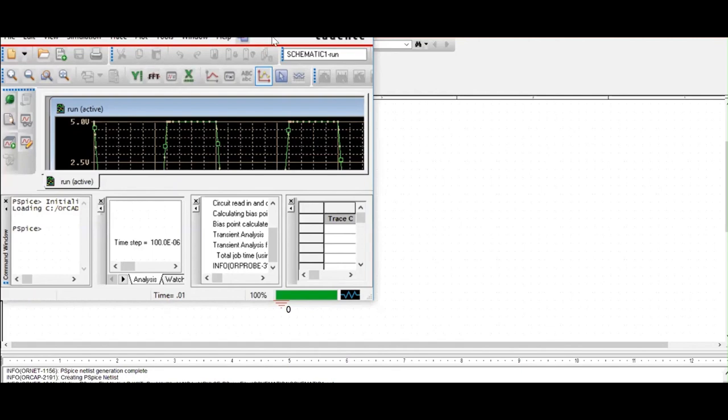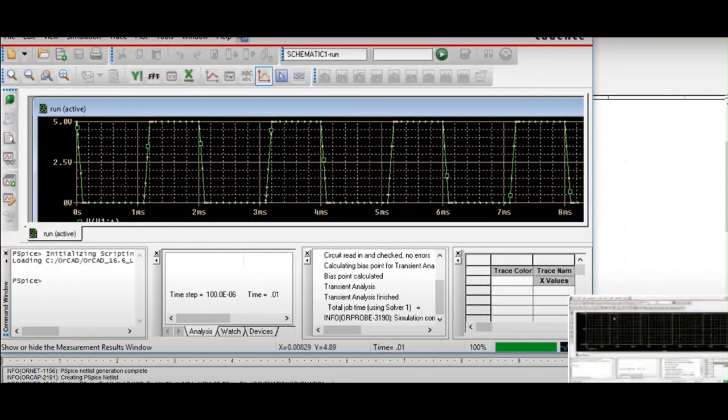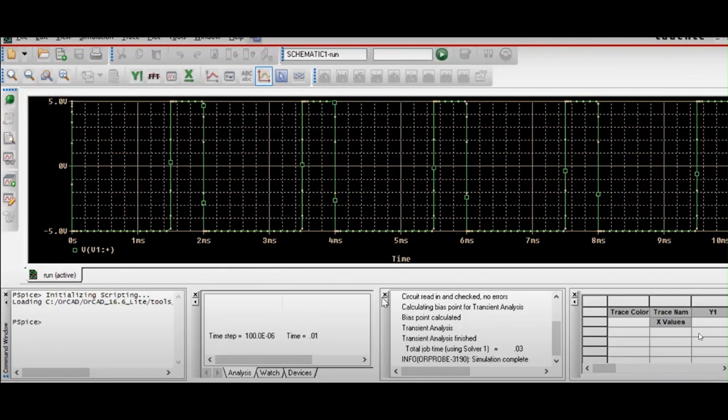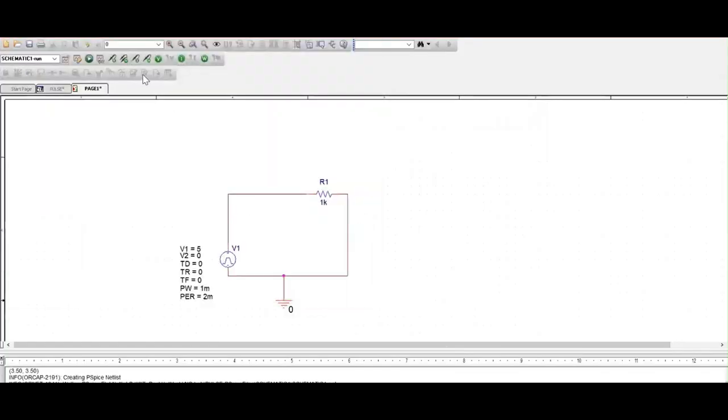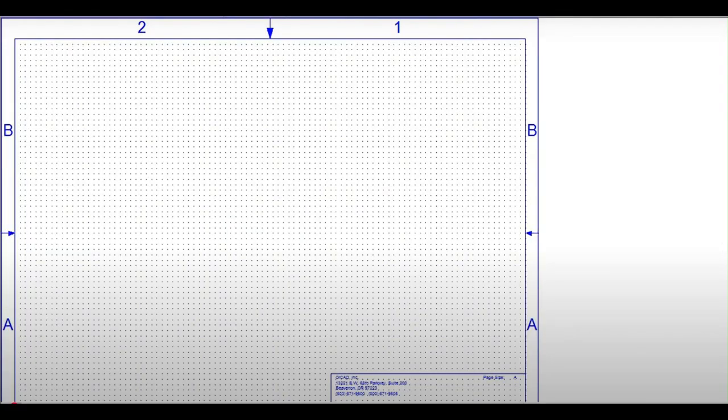Let's go for R-2R, which is a DAC, which basically converts digital data to analog data. If you give it a digital digit like 100, which is equal to 4, it will give you an equivalent voltage, which is 4. So let's give operational amplifier here, and you can see the internal voltage is already given here, and you don't need to give it externally, and there's an internal connection here.